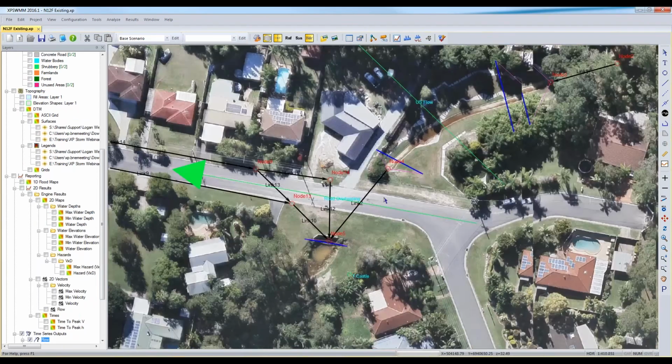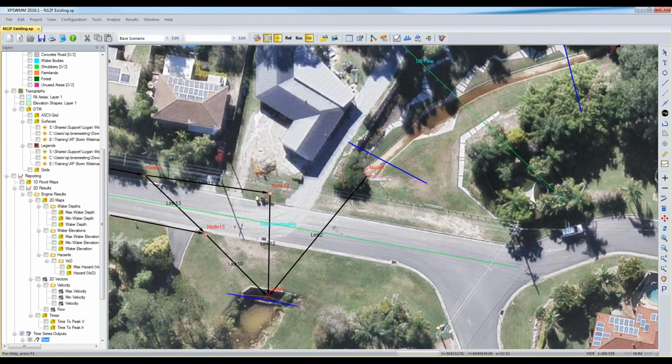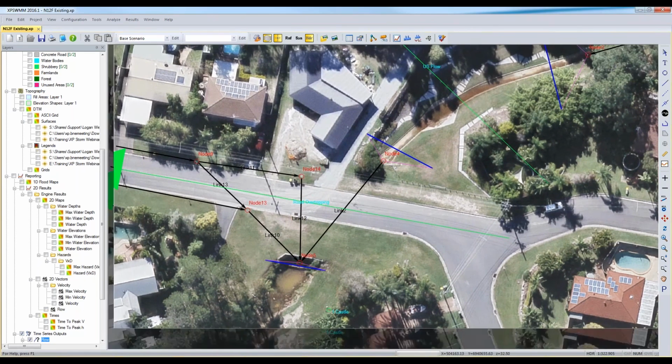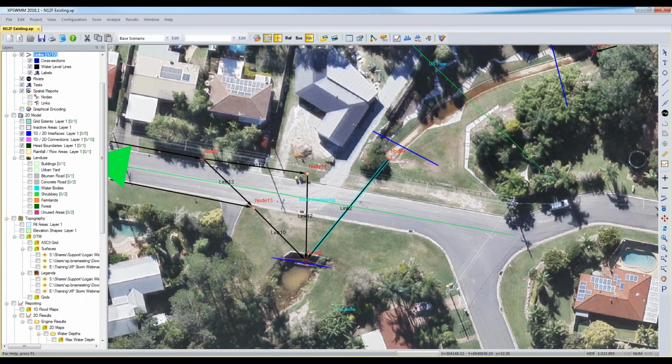You can see here I've used quite large interface lines. Now, when we didn't have interface lines, XP was bombing out, coming out with a 2D unstable. It's really a protection tool. When you first start modelling, you think, these errors, they're killing me, but it means that there's an instability in the model.